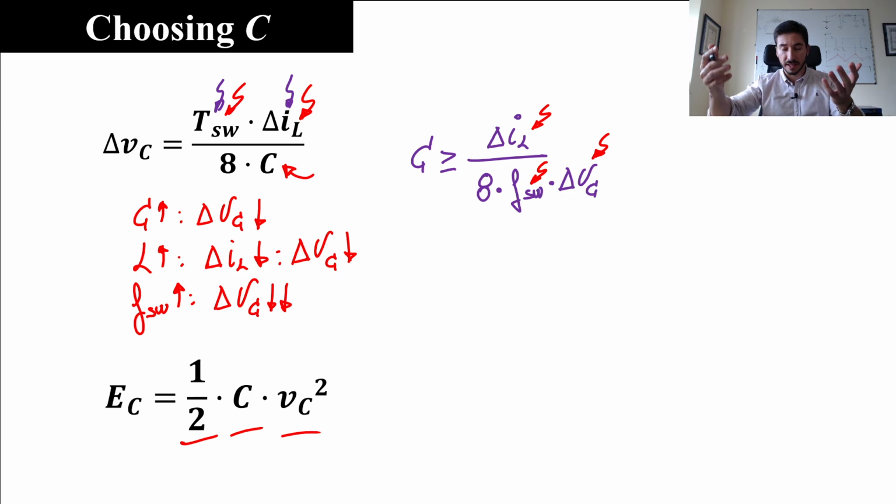So that's why we choose a capacitor with a voltage rating close to the voltage it is going to block in the circuit. For instance, if the output voltage is 5, you want to choose a capacitor able to block 7, 10 volts, perhaps 20, but we don't choose a capacitor of 400 volts, because the amount of energy that this capacitor is able to store is much higher than the one that you need in your circuit, and you penalize a lot the size of the topology.